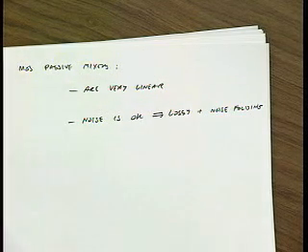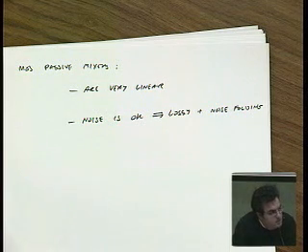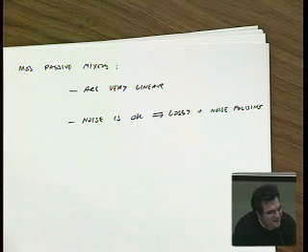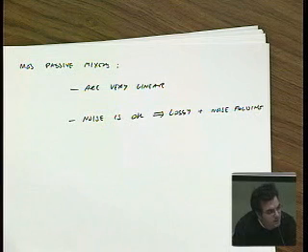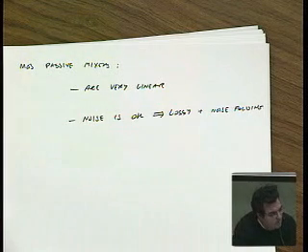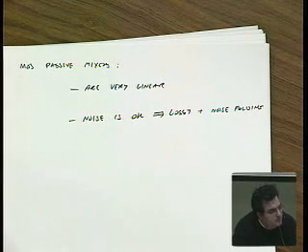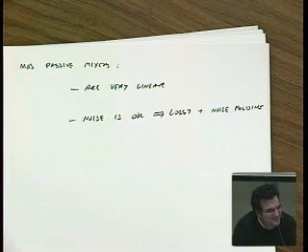Yes? What limits the linearity of passive mixer? Is it the charge injection? It's actually quite complicated. If you're interested, I can send you a PhD thesis on the topic. Because it's pretty linear to begin with, to really get at the nonlinearity, you have to dig deep. You could do Volterra series analysis on the device nonlinearities. It's the nonlinear junction cap and also the nonlinear behavior of a short channel device. It's not perfectly square law. So all these things contribute to the nonlinearity. Yeah. Okay. Any other simpler questions? Okay.